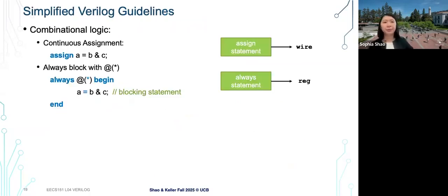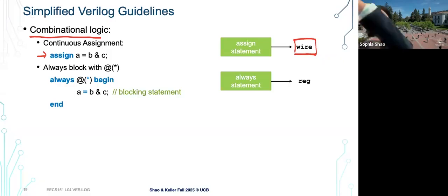So just a quick recap, when we talk about Verilog, so far we have been looking at combinational logic. There are generally two very high level ways of defining combinational logic. You can use an assign statement, which is very handy to directly assign components. One thing you will notice is that whenever you use an assign statement, you always assign a value to a wire. And to Justin's question earlier, we cannot assign to the same wire with different assignments, so we need to instantiate different wires. But it's always a wire here.